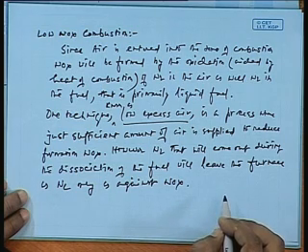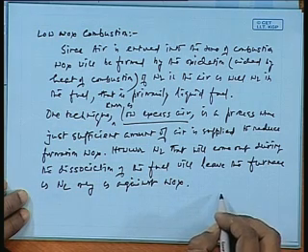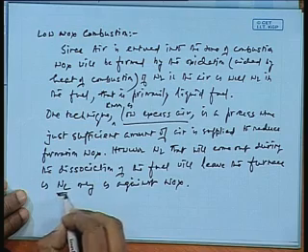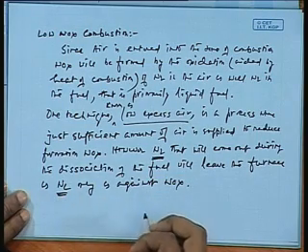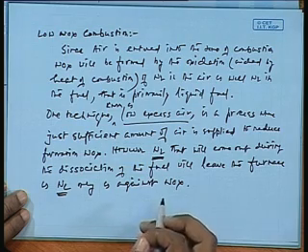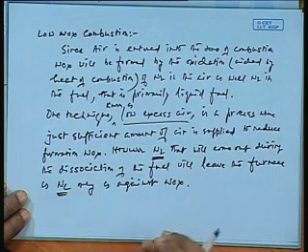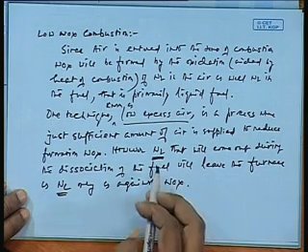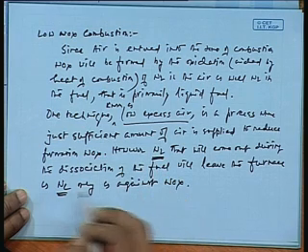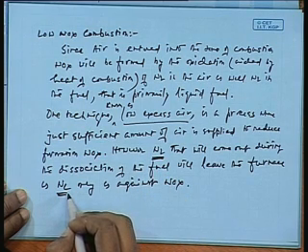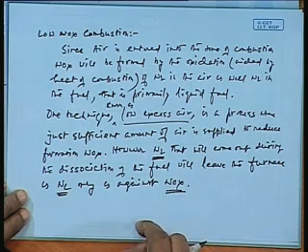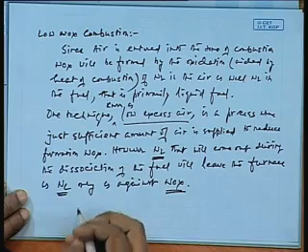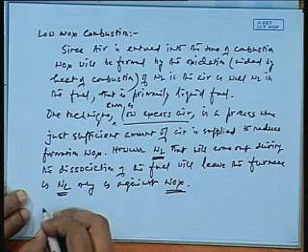However, N2 will come out during the dissociation of fuel. We leave the furnace as N2 only. So N2 would not be changed. The air would be supplied in such a quantity that the combustion takes place, but yet N2 does not get oxidized into NOx, and leaves the furnace as N2 as against NOx in other processes. This is one technique that is called low excess air.